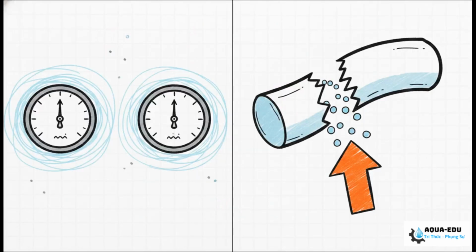The operational manual highlights a very specific set of symptoms for this. We see a decline in salt rejection, a noticeable drop in resistivity, and rising conductivity. But the crucial point is this: your operating pressure and temperature remain totally stable. When your pressure is completely fine, but your quality is tanking, it definitively proves the membrane's physical integrity or its active surface has been compromised. It's just no longer a barrier.